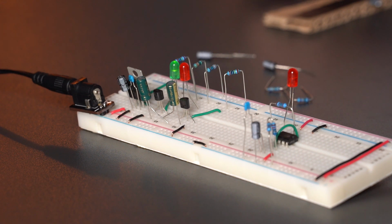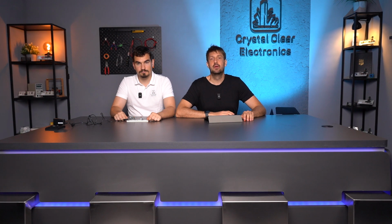Touch the COM wire of the multimeter to the ground of the circuit, the positive wire to the base of one of the transistors, and observe how the base voltage changes. When the LED in the collector circuit of the transistor extinguishes, the voltage will be negative, about the difference of the supply voltage and the LED opening voltage, and then slowly grows up to about 0.7 volts, then the LED will light up. This complies exactly with the principle of operation of the circuit.